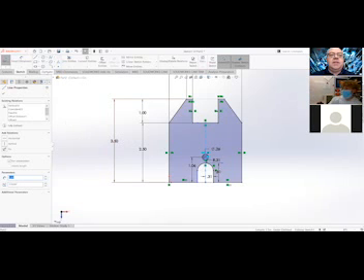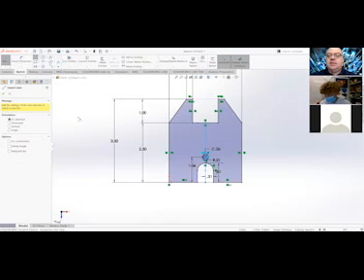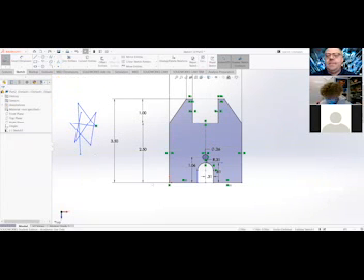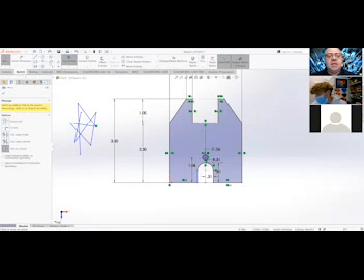I'm going to throw some lines on here and let's see if we can guess what the gyrations mean. If I've got a bunch of lines, and in this case you might have the vertical lines going all the way up, a horizontal line going across and one across the bottom. When you do trim entities, the one I use probably 80% of the time is trim to closest.